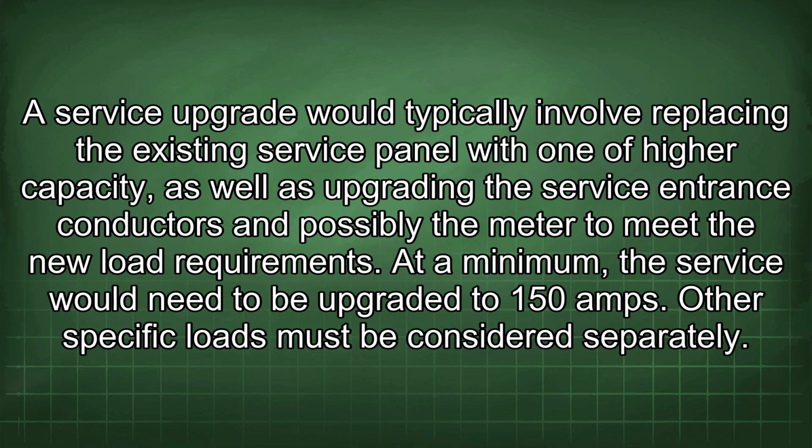A service upgrade would typically involve replacing the existing service panel with one of higher capacity, as well as upgrading the service entrance conductors and possibly the meter to meet the new load requirements. At minimum, the service would need to be upgraded to 150 amps. Other specific loads must be considered separately.